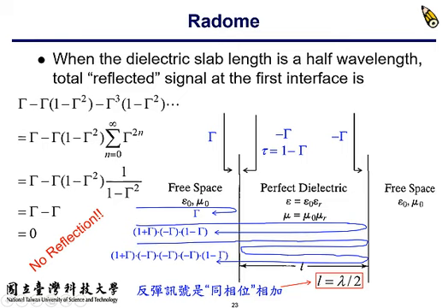So back to the first three terms. We know that the magnitude of the first term is proportional to the reflection coefficient. The second term is actually the transmission coefficient tau, okay? Reflection coefficient gamma, tau equals 1 plus gamma. So this is the transmission coefficient at the 1-2 interface. How about this? Minus gamma. This is the reflection coefficient at the 2-3 interface.